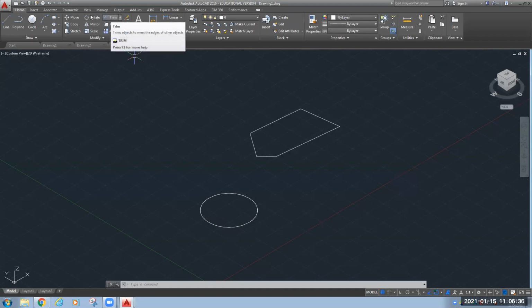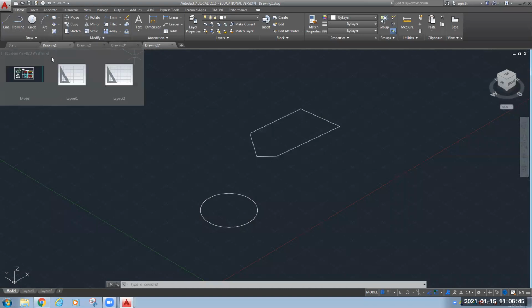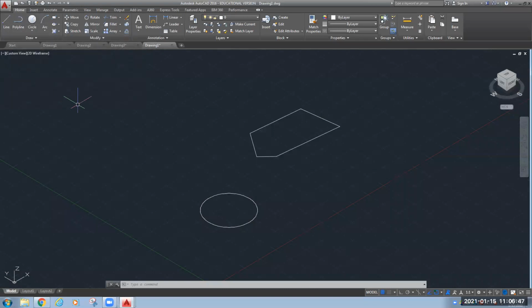Now, I want the menu items for drawing 3D figures. How will I bring the 3D commands menu here? For that, at the bottom right side, in the line where you can see your ortho, O snap, in that line you will see a symbol representing a small gear.